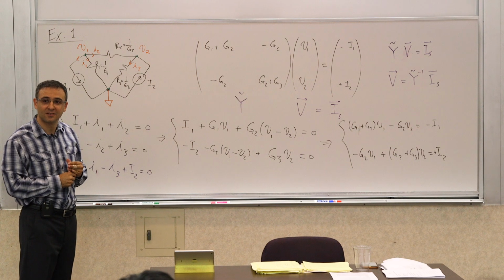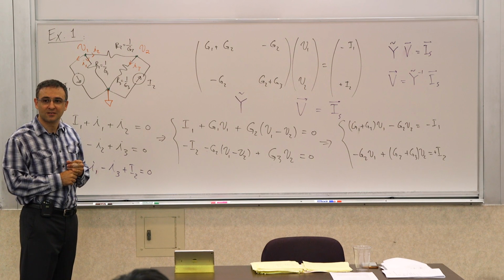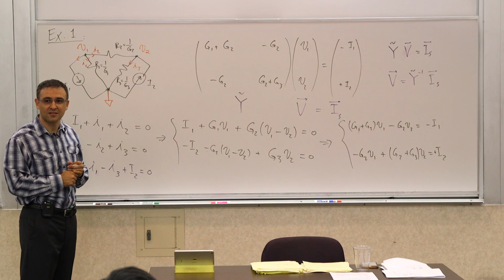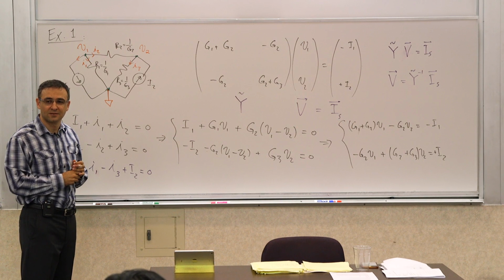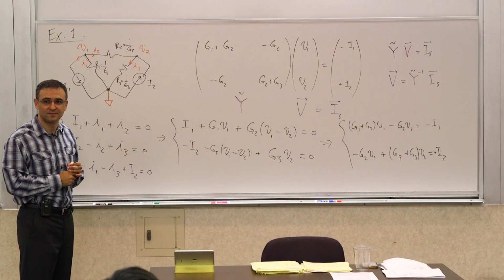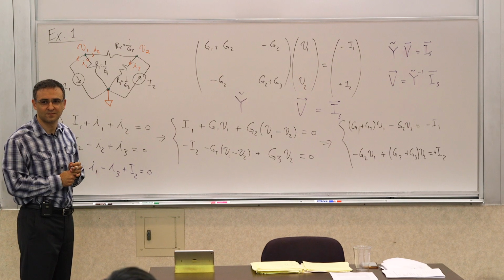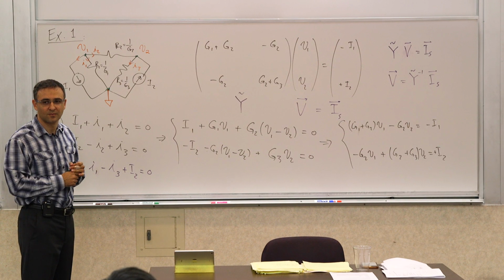The diagonal from top left to bottom right would have the sums of the conductances, and on the edges, depending on the signage of the ones on the diagonal, you would have a certain number of the middle term of the conductances.